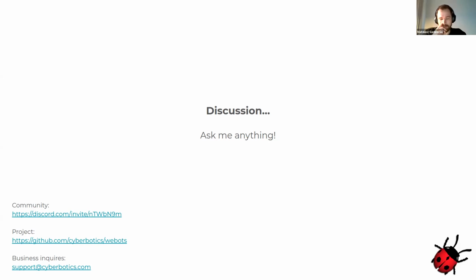So is this a plugin, or is it part of Webots? It's not part of Webots. We were developing an external, internal project, and we figured it would be nice to adapt IKFast so we can use it with Python. Webots allows you to export URDF. You take that URDF, you pass it to IKFast, and it generates solutions. It actually generates a Python library. So what we developed there is a Docker image that has all the tools necessary to generate the IKFast library and a Python interface for it.